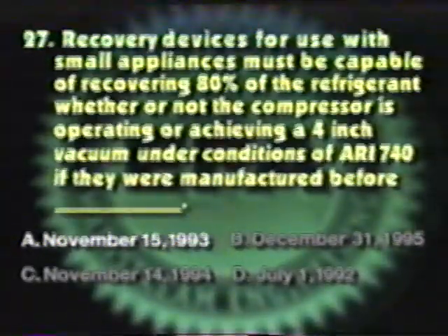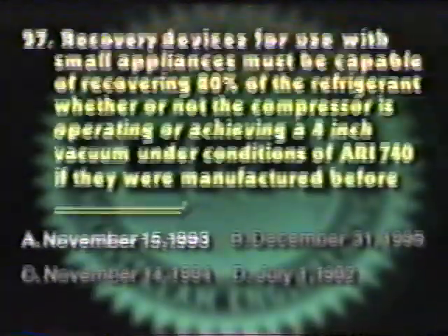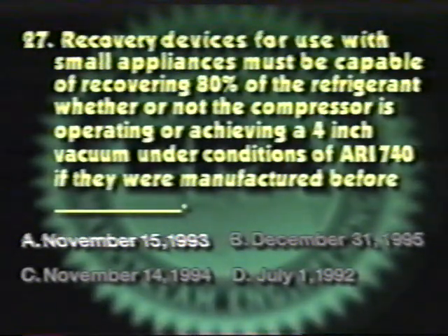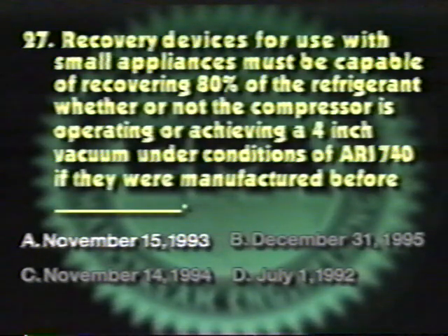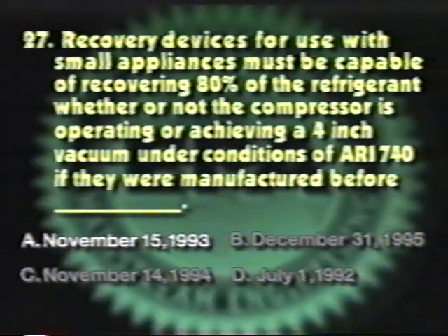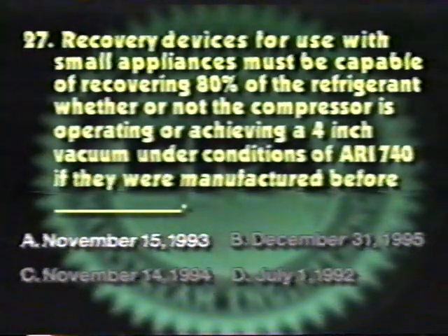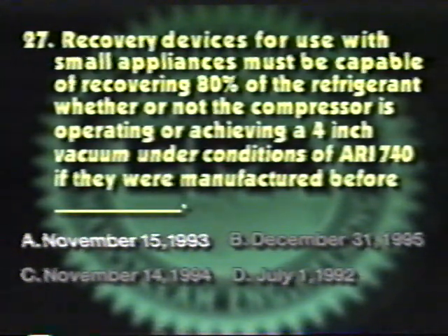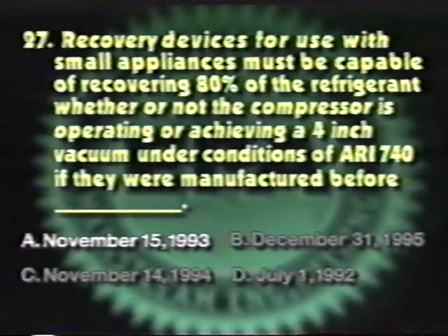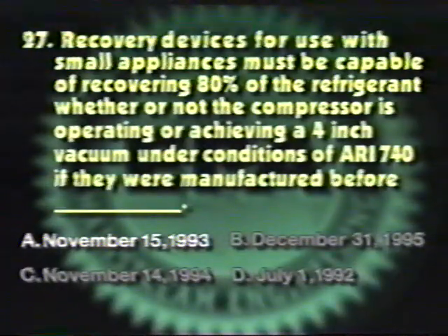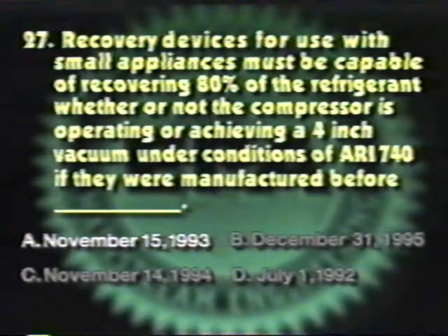You should know the differences between the recovery requirements for recovery equipment manufactured both before and after November 15, 1993. Note that the November 15, 1993 date refers to the date the recovery equipment was manufactured, not the date the equipment being serviced was manufactured. Be sure to review the section on evacuation requirements of small appliances.